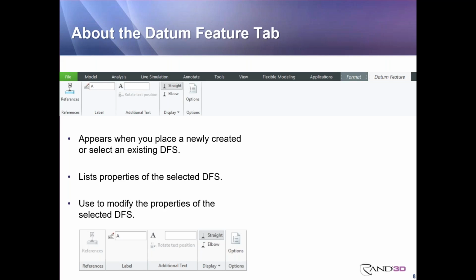When you're talking about ISO standards, of course, you can use a combination of capital letters. Numbers and special characters are not allowed. Any number of characters in ISO standards is allowed, and the letters like I, O, Q, and X are not allowed. So I, O, and Q are not allowed in either ASME standards or ISO standards. And additionally, ISO standards does not allow the letter X. The identifiers that you specify, if you specify them and they are valid, the labels appear highlighted.